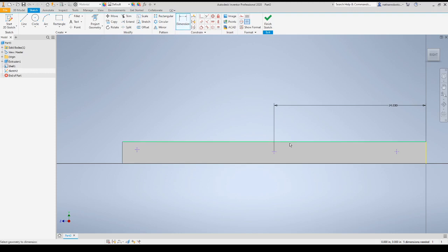Like I said, I can grab the dimension tool. You don't have to grab it every time, I'm just doing that to show you. Edge, point, here. Now, center of the tube would be 1 inch, but on these 6-wheel drive chassis, it's common practice to run a little bit of a drop center, meaning the middle wheel is a little bit lower and you get a little bit of rock. That reduces some turn scrub, which is the amount of friction involved in turning. So we're just going to do 1.1 from the top on that. This one will come down and we'll do 1 inch.